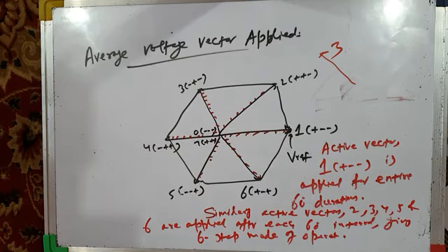And then we increased the modulation index. We then studied over-modulation with slightly higher modulation index, M equal to 1.2. We took the range 1.15 less than M less than 2. We saw that the inverter output voltage slightly increases, and the distortion level further increases.